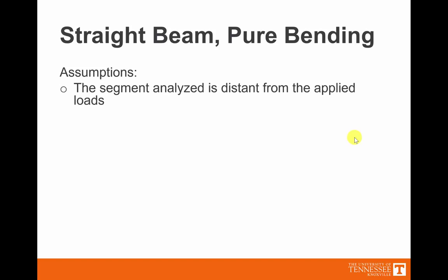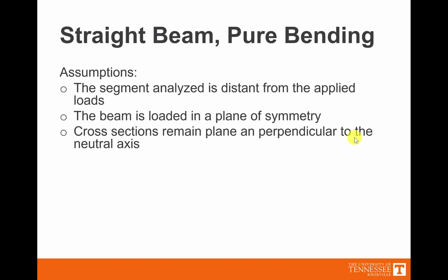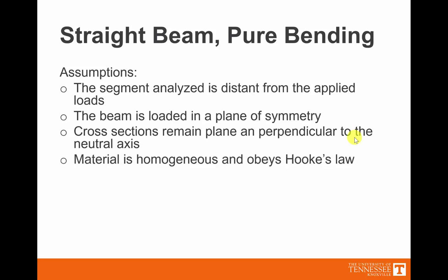The segment again is analyzed a little bit away from the applied loads. The beam is loaded in a plane of symmetry. When we put a moment on it, we're putting a moment on in a plane of symmetry. The cross-sectional sections remain in plane perpendicular to the neutral axis. In other words, we're not deflecting it too far.